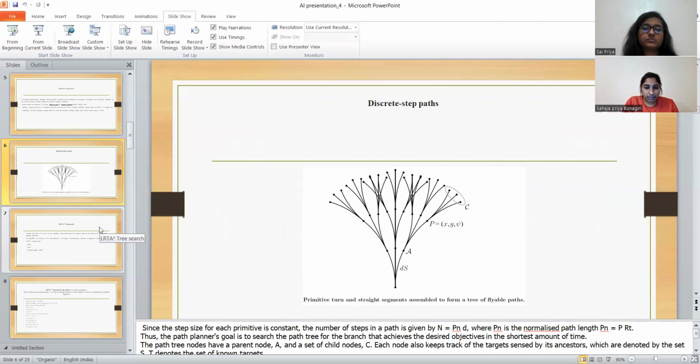Given that there is a finite number of nodes, there are practical restrictions to the growth of a tree, which expands exponentially with the depth of the tree. The depth of the tree is limited by computer memory. The step length and tree depth affect the path planning, tree search speed, and the quality of the final path plan. Their importance will be explored further in Section 3, which describes the tree search. Taking everything into account, the easiest method for constructing the path tree is to produce a fixed depth path tree. Next slide.